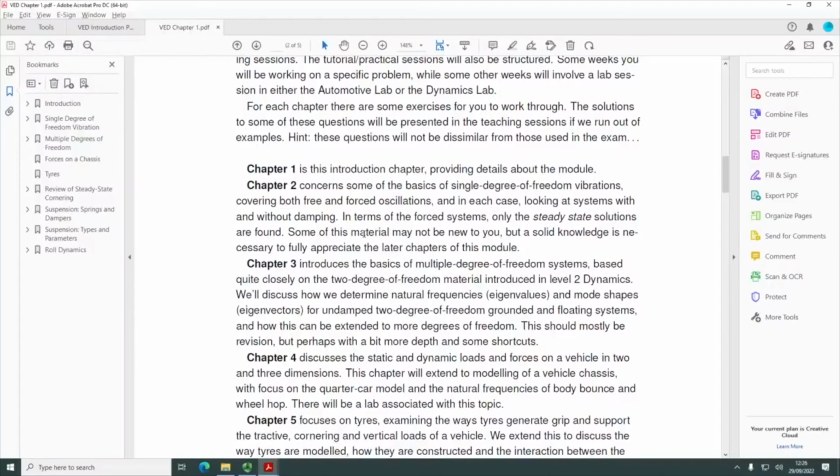So clearly there are 2 natural frequencies and 2 mode shapes, like all 2 degree of freedom systems. And those mode shapes, in particular in vehicles, have a particular name. So you've got body bounce, which is the body oscillating, and then you've got what's known as wheel hop, where the wheel is oscillating. Like I said, we'll look at that theoretically, but we'll also look at that in the lab with the rig down there, which is the intention. And we can model it using MATLAB, and I'll do that as well.